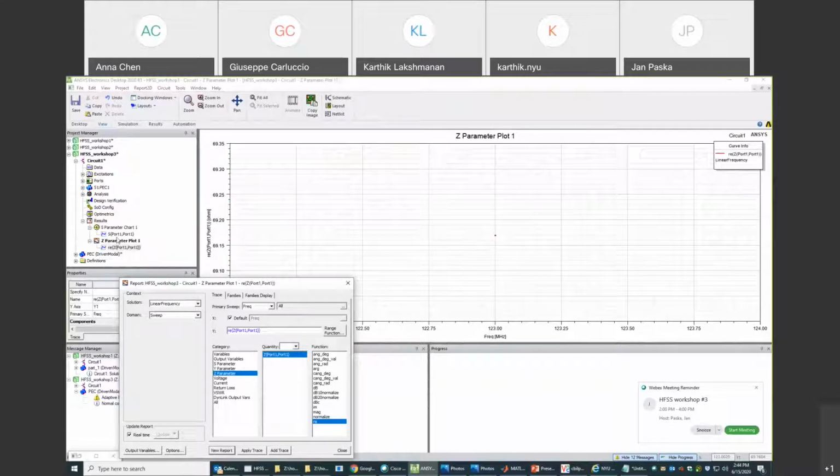So as expected. We're not finished, we need to get to 50 ohms, but you can see that in 4 steps we can get kind of close. And we have done all this in post-processing, and we did not have to re-simulate the original 3-dimensional simulation, which can take a long time.